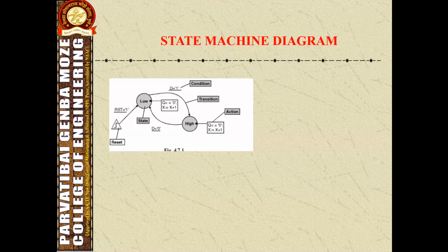So there are two basic kinds of action: state action and transition action. State action is defined for the state and is performed when the machine transitions to a specific state. The behavior of combinational and registered signals or ports involved in a state action is the same. The HDL statements defined in the state action are executed on the active clock edge. The state action can be used to model the Moore machines.